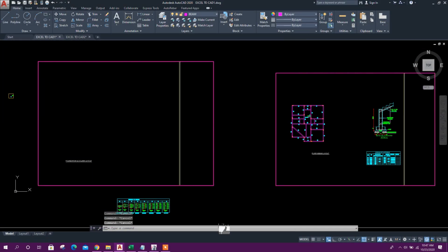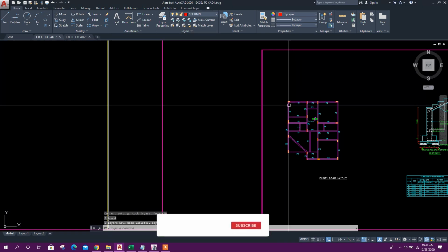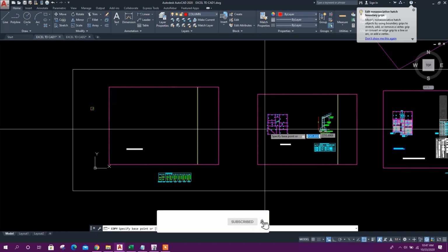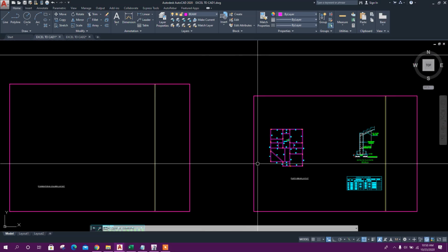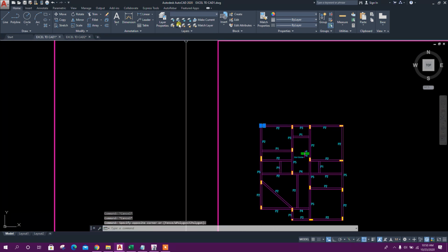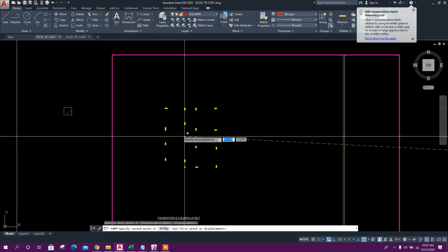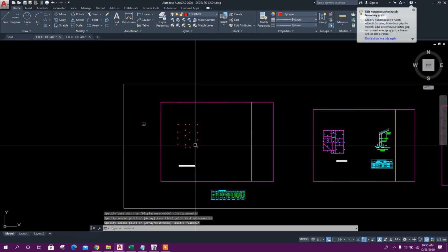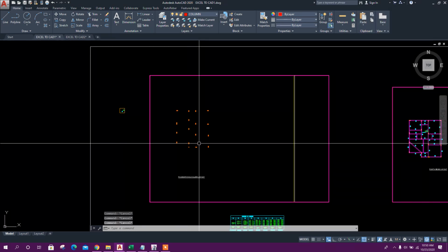After designing beam columns, we will copy the column layers for creating the column foundation layout. After finishing beam column design, we will copy the column layers to create the foundation and column layout. We can do it very easily using ETABS reaction values in the Excel sheet.